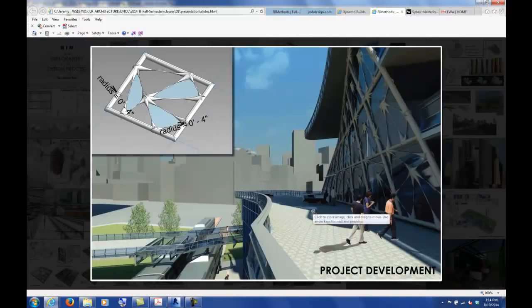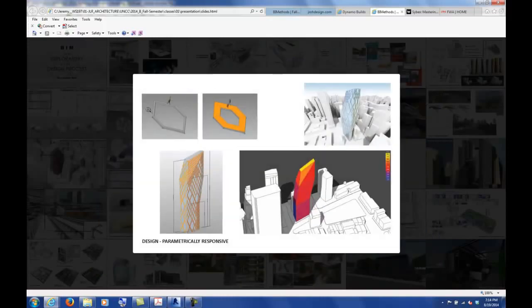One last thing is, again, we can take that facade idea or that adaptive component, and you can apply it not only to canopies, but it could be applied to a facade. You could get these real complex looking structures with just making one component that eventually repeats over the surface over and over again.